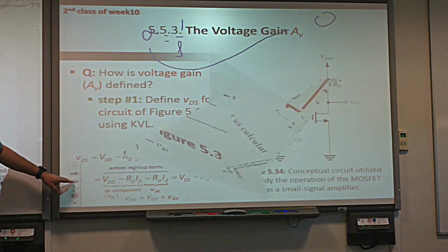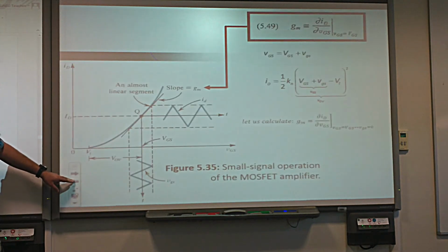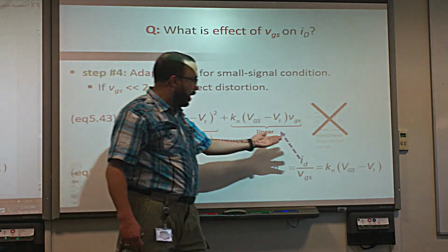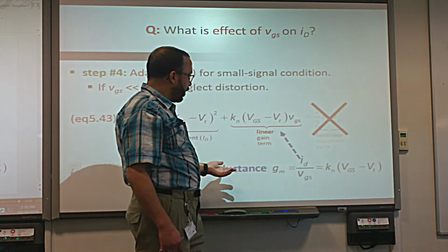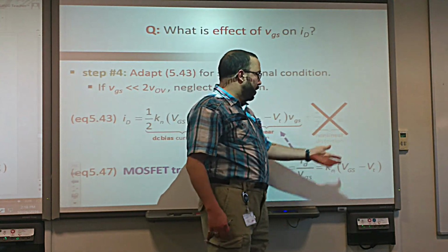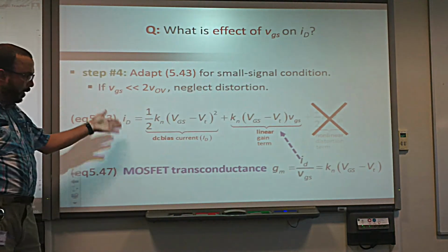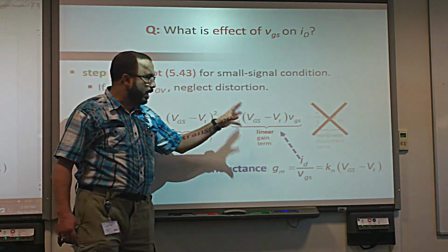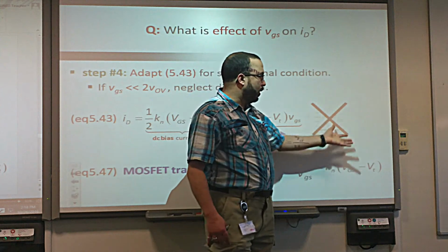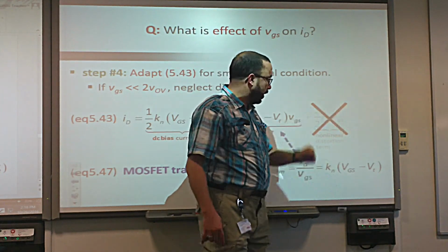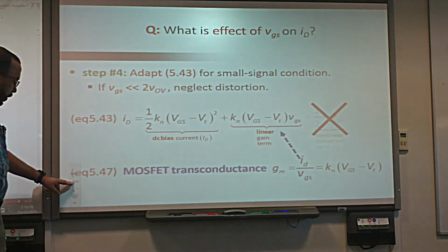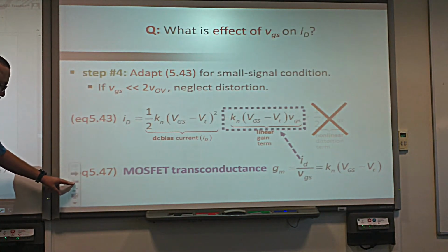And we have approached this problem in two ways. There's one way using the small signal analysis, and for small signal analysis we said that to find the transconductance is basically to develop the equation for ID which is the instantaneous, and then we separate the DC from AC, and then we said to get rid of the nonlinear distortion here, or to make it as small as possible compared to the linear part, what we do, we make an assumption.